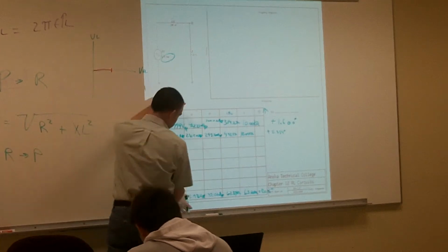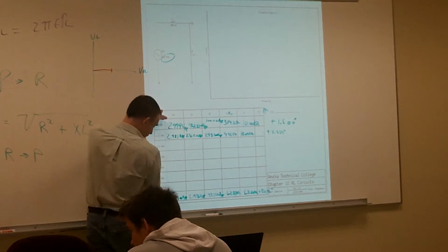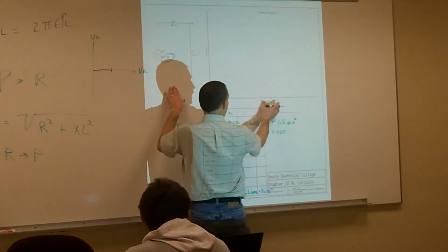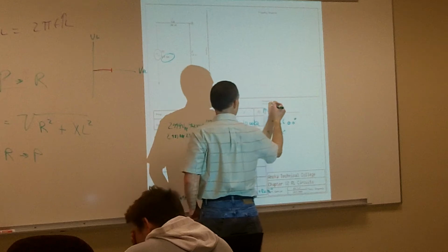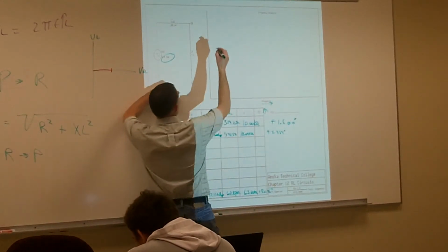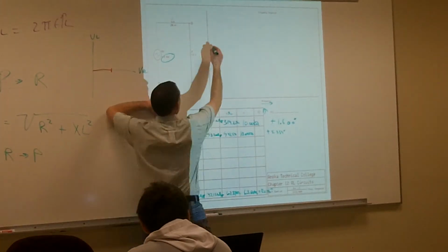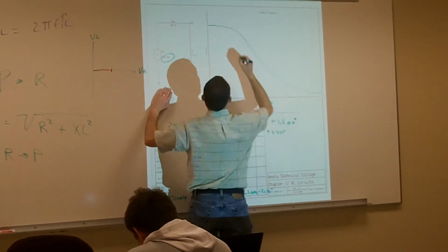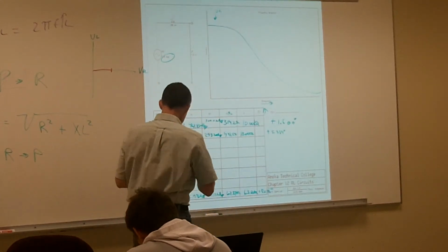So you can kind of see that as I start to increase my frequency, VR starts out very high and then goes very low. So when we're doing our frequency response chart, as I go this way, I'm increasing my frequency. At my low frequency, my VR starts out very high, and then we're going to get a curve that looks something like this. And here's our VR.